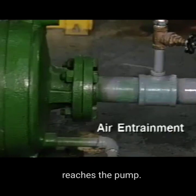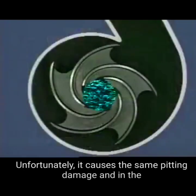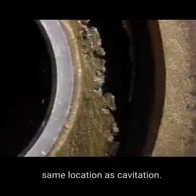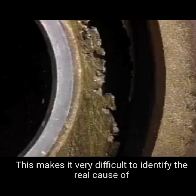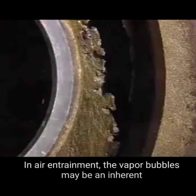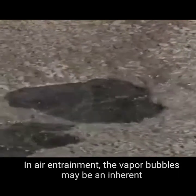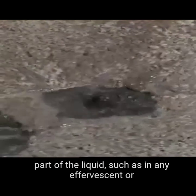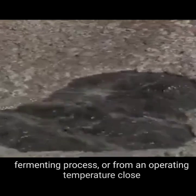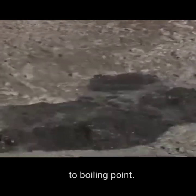Air entrainment defines a wide variety of conditions where the vapor bubbles are already in the liquid before it reaches the pump. Unfortunately, it causes the same pitting damage and in the same location as cavitation. This makes it very difficult to identify the real cause of the damage, particularly as they can happen at the same time. In air entrainment, the vapor bubbles may be an inherent part of the liquid, such as in any effervescent or fermenting process, or from an operating temperature close to boiling point.